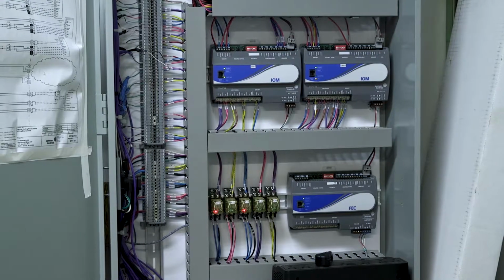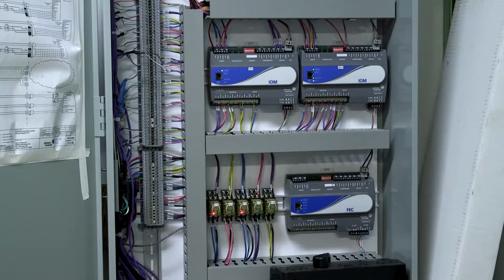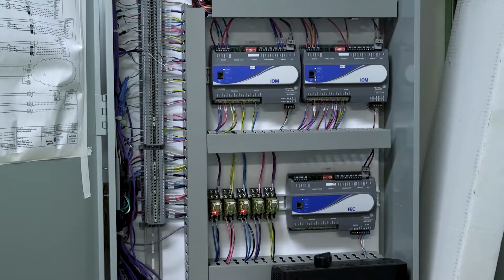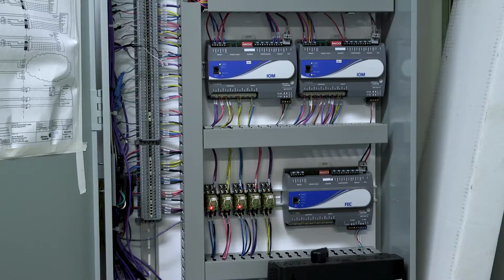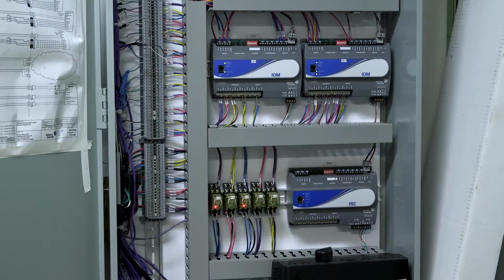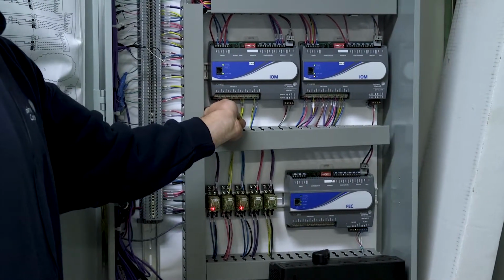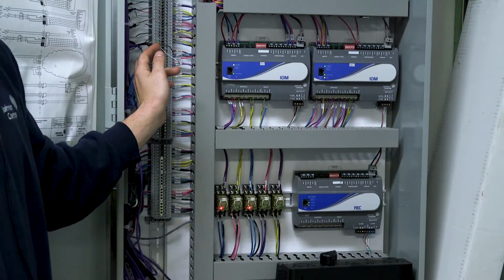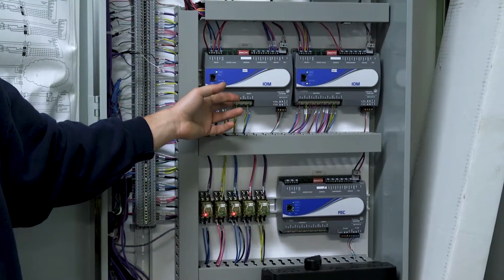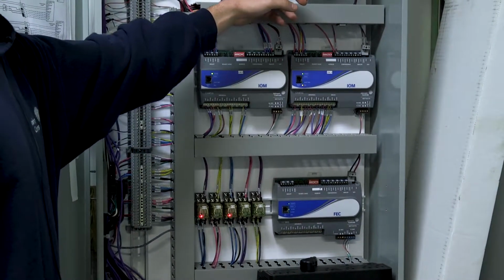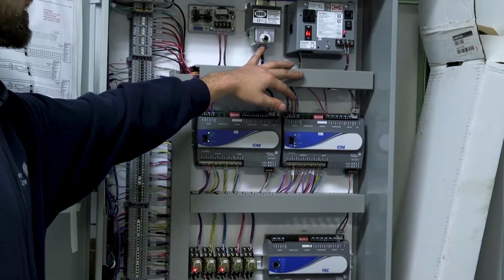All right, so this one has 3 IOMs, an FEC on the bottom. I don't know what really the purpose of that is, besides probably memory. That's it, it's just memory. But as you can see, you got all your wires labeled. On the bottom here, you got labeled to what terminal it goes to on your terminal strip. And on your terminal strip side, you have what input or output it goes to on the actual controller itself. Obviously, you got your transformer up here, resets on there, another transformer here with a reset as well.